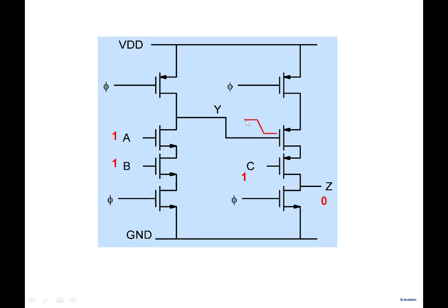So now note that if this is 1, and let's say 1 is incorrect, it doesn't do anything to the PMOS, PMOS is off. And once it goes to 0, then of course it turns the PMOS on and proper operation takes place. So the idea is that we build one dynamic gate with NMOSes that you see here, and then we follow it up with another gate where it is PMOS. You can see that these are sort of complementary if we also invert this. If we also invert this, then you can see it's complementary to this particular one here.